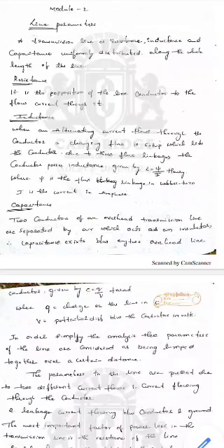We know that during the transmission of power over overhead lines, we are using different transmission lines. For example, if you consider two transmission lines laid parallelly for the transmission of power, there will be a certain distance in between them. In between the two transmission lines, air acts as an insulator, the medium which separates them. So there exists a capacitance between these two transmission line conductors.